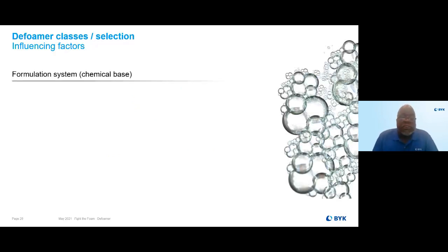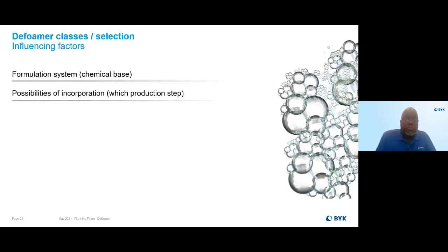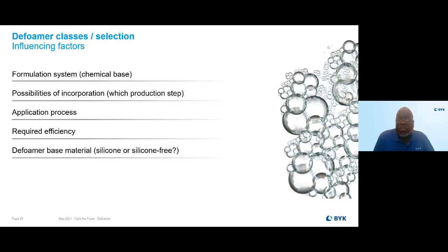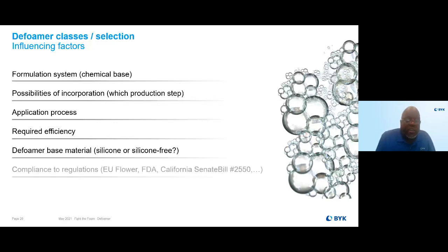Some of our other influencing factors are the formulation style with chemicals, possibilities, which production step, the application process, how it's going to be used, required efficiency, and defoamer base, whether silicone or silicone-free, and one that is often forgotten is compliance. Are you under any special restrictions for EU, FDA, or in the crazy world of California?